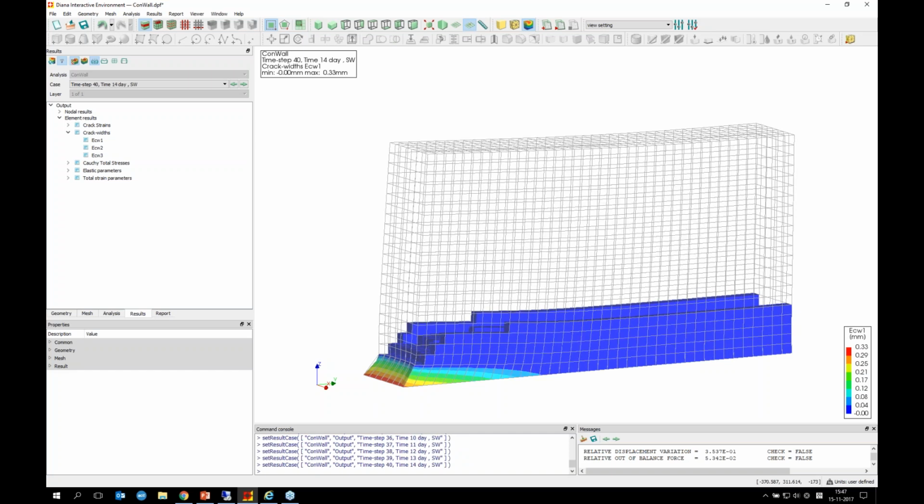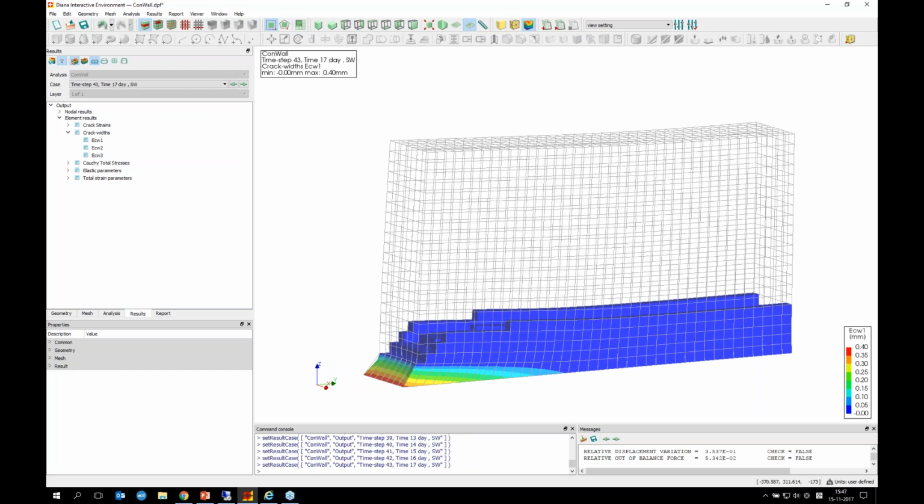And then along with the volumetric shrinkage of this concrete, you have many cracks here. But actually, this is a downside of this fast modeling. I neglected this bottom part. Actually, it is not fully fixed. Maybe if you introduce a boundary interface at the bottom of your concrete, you may get some displacement here at the bottom, and then you will get less stress concentration.